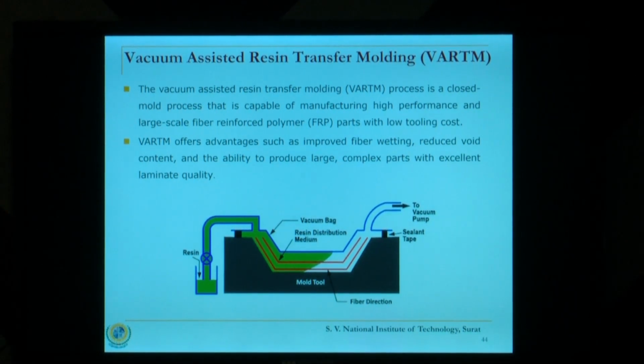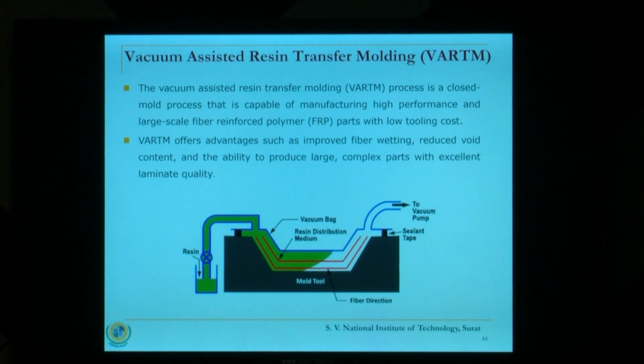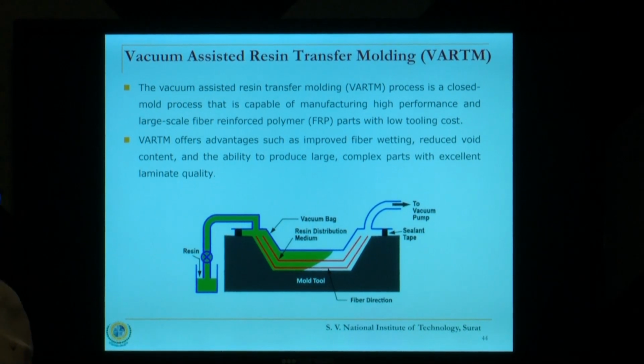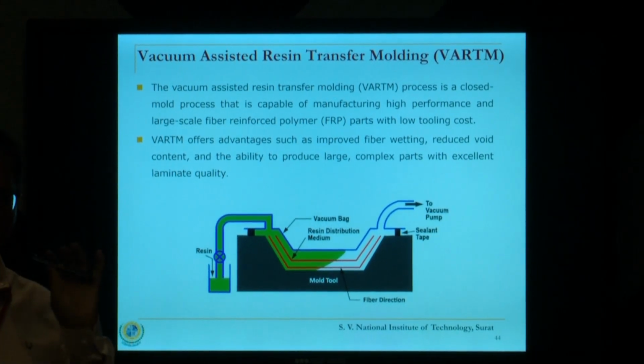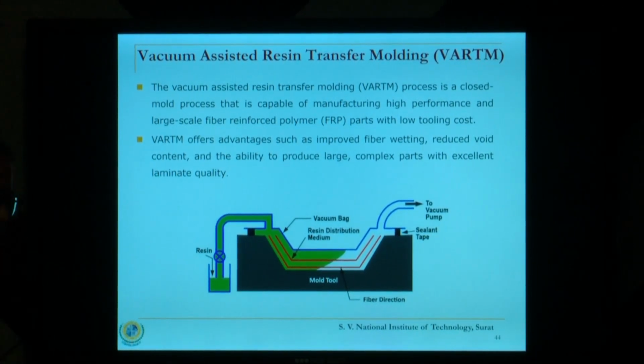So here, what we want to do is seal the entire structure, place the fibers of our requirement with the required orientation or required sequence into it, and then create vacuum.